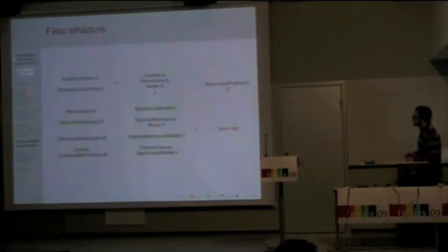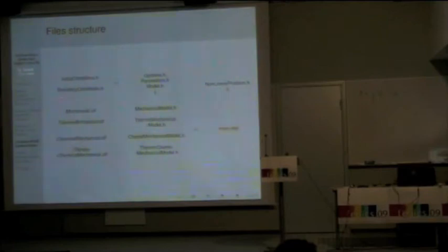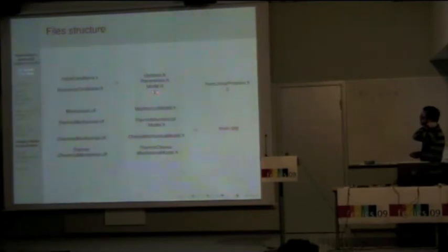These are header files we use to specify what the UFL files require, and all these take definition of some classes from this file, model.h, this header file. We need also to provide some parameters for the problem, and also boundary conditions and the initial conditions, which are absorbed by this header file.